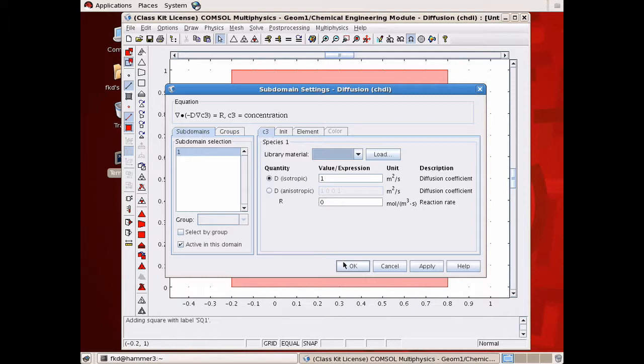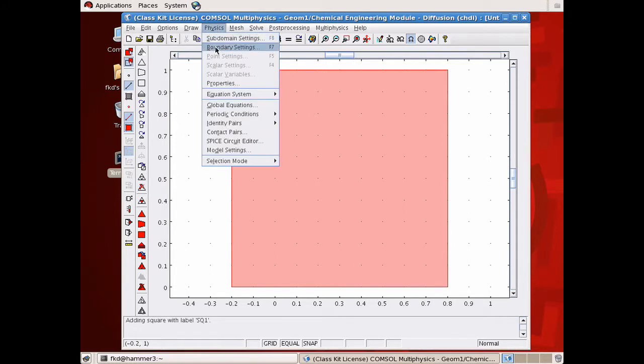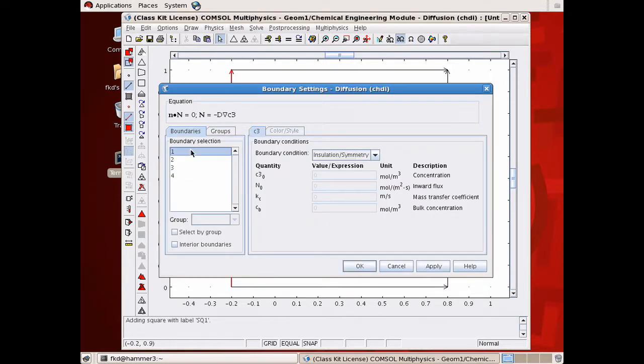And I'm going to accept those, which is fine. And then I'm going to put some boundary conditions on it, which are going to be upstream on the left side. It's going to be a head of 1. I mean head because I'm using it in that. It's insulated on both sides, and the downstream head is 0. Okay.